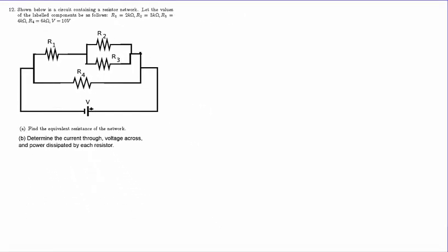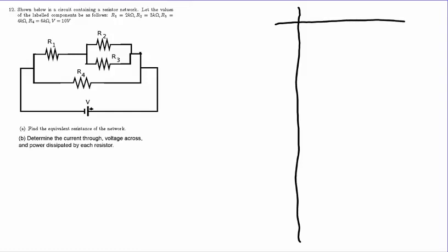each resistor. In this problem, we recognize that we are analyzing a resistor network, and we also know that the simplest way to analyze this is to do so in the form of a table. Because the equation that governs simple resistors is V equals IR, the table will contain these three quantities as the headings. We'll list them as resistance, voltage, and current. Finally, since this problem also asks us to calculate the power dissipated in each resistor, we'll make one extra column to this table, the power column.